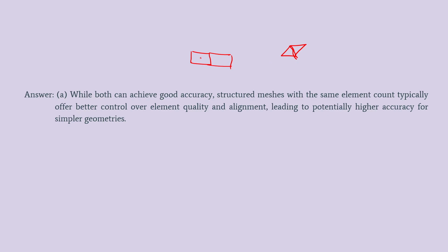So even computing the inter-centroidal distance in structured mesh will be easier compared to finding it here, because here it will be more inclined, and also finding the geometric proportions of the intercentroidal length, the base length, all such things will be difficult in unstructured mesh, whereas in structured mesh all such calculations will be easy, because in structured mesh it will be somewhat correlated to our coordinate axis.